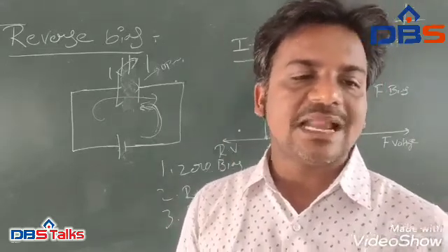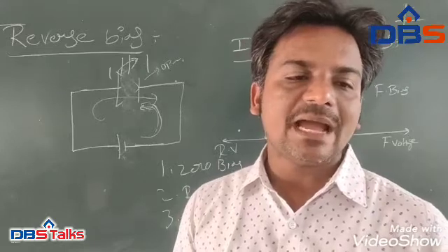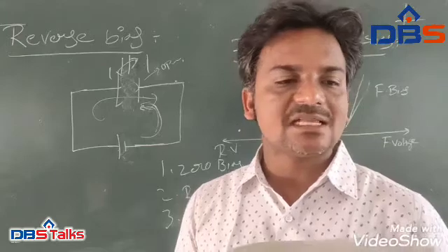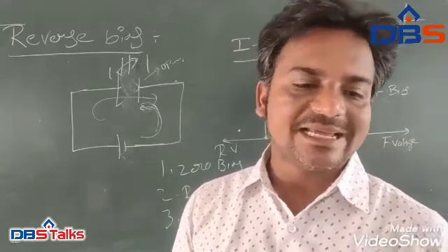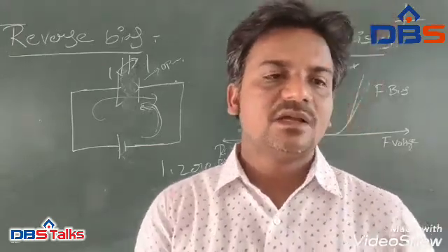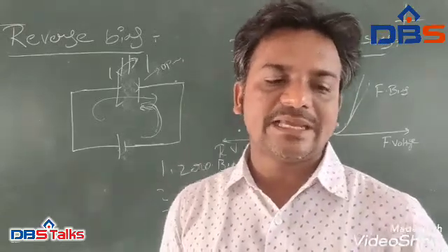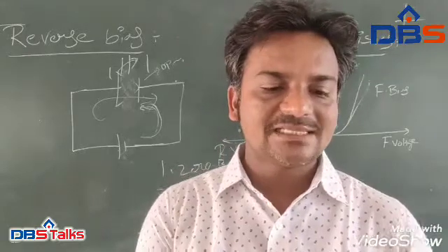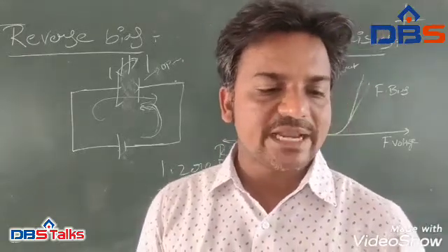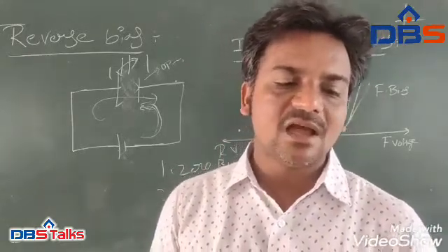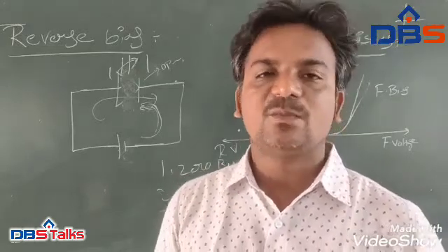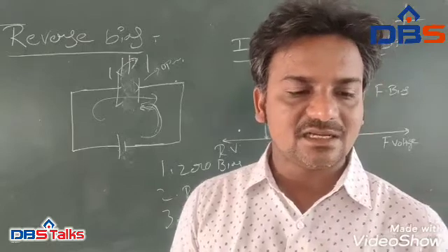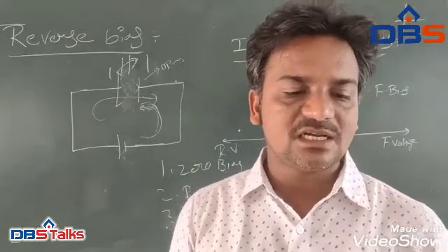This transfer of electrons and holes back and forth across the PN junction is known as diffusion within the PN junction diode. The potential barrier that now exists prevents the diffusion of any more majority carriers across the junction, while the potential barrier helps minority carriers drift across the junction.